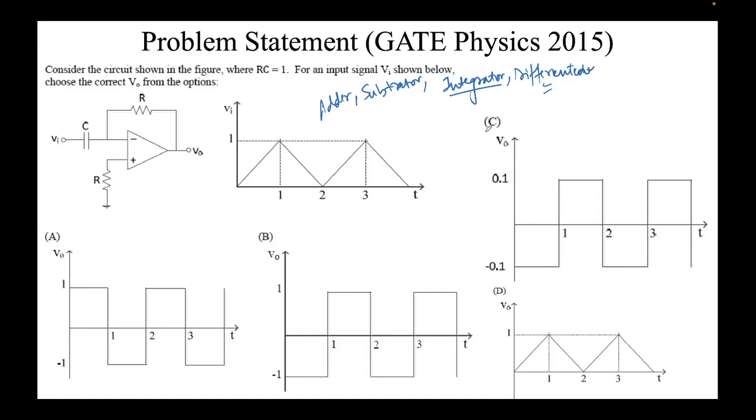What I do is I know KVL, I know KCL, I know Op-Amp. That's the only 3 things I know. So based on that, I'll solve the problem. You don't have to remember it, because I told you every question I am doing the same thing. KCL at inverting input, KCL at non-inverting input, and Ohm's law. That's it. Nothing else. I'm not even changing the approach. Last class we did 5 questions. This class I'm doing 5 questions, and in the next class also my approach will remain the same. I just have one approach. It solves every problem of Op-Amp every time.